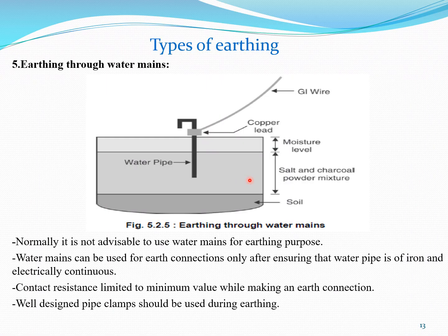Just the water pipes which are buried much below the ground are used for the earthing purpose, and hence the earthing wire is wound on that water pipe only. Again I repeat, such a type of earthing system is not advisable, but where we are not having the option, we can use this existing system for the earthing purpose.